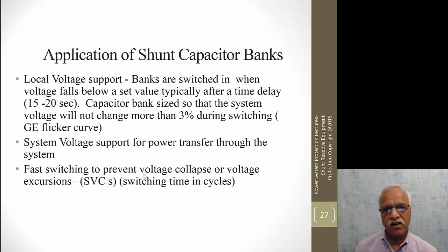This has come from the historical GE flicker curve of the 1950s, where they conducted an experiment to see what causes irritation to people. And even now, this is used in the industry as a criterion for sizing the capacitor banks.